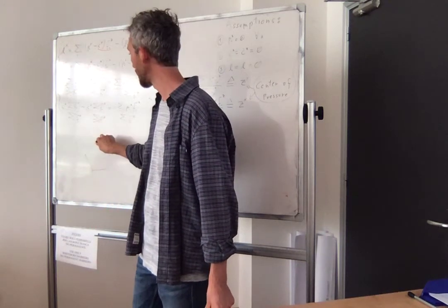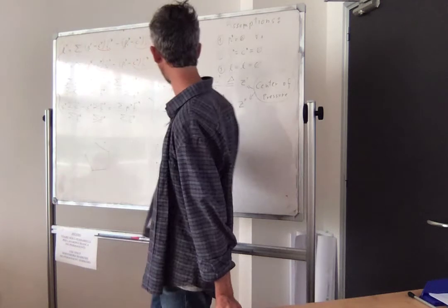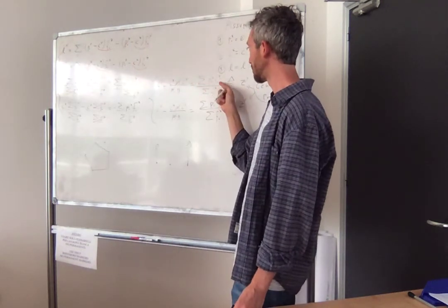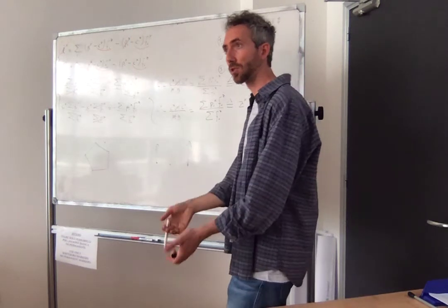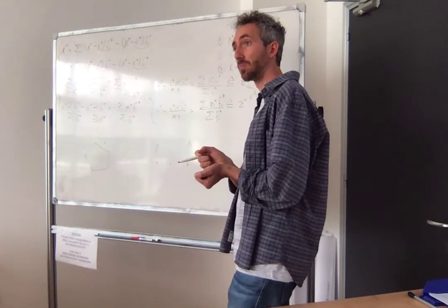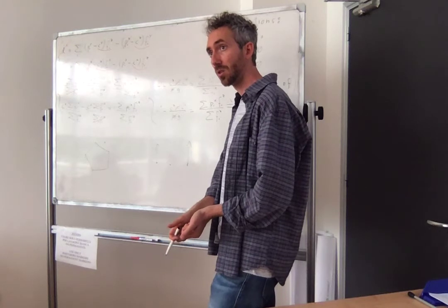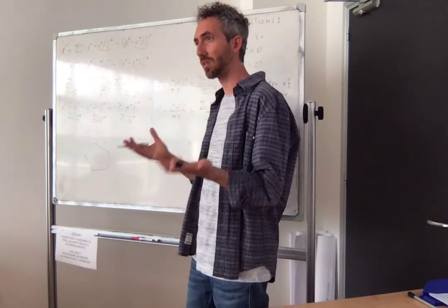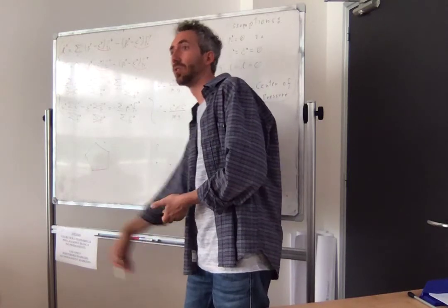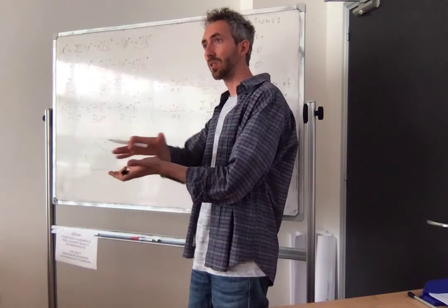It cannot go outside. To go outside, I would need a negative weight, which corresponds to a negative normal force, which would be a force that pulls on the ground. But since I can only push, I'm going to stay inside, which is physically consistent. My center of pressure cannot go outside my contact surface.